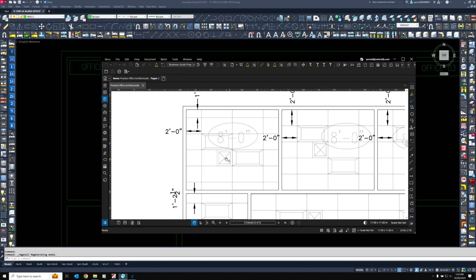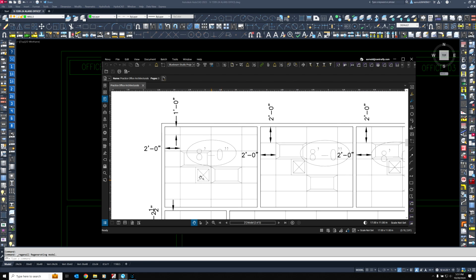This is not a super accurate reflection of what you would see in a room like this, just so you know. When they put a ceiling in a room, this is probably the last way they'll do it, because you have partial tiles on all 4 sides. And this was really just for me to make you use the tools more. That being said, notice this T-bar, the grid, is 1 foot from the north wall and 2 foot from the west wall. So that's how we want to lay this out.